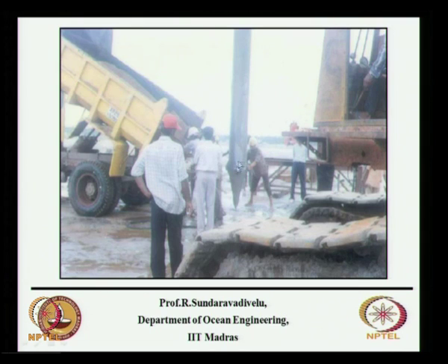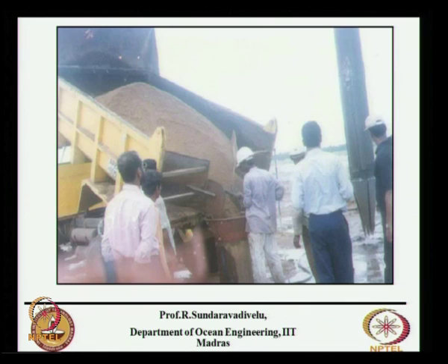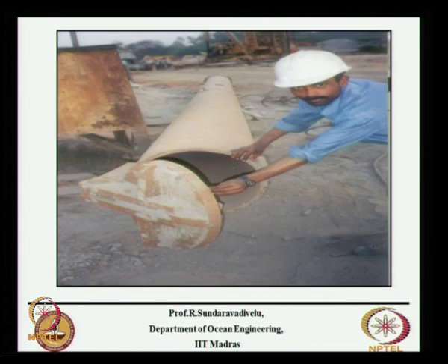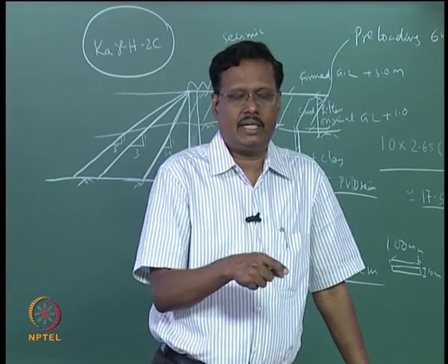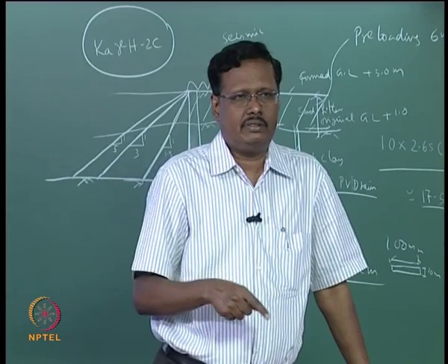So here you are seeing, you have pile driving equipment, what you do is you drive it and there is a bottom opening. You see here this is a steel casing with a bottom opening. There is an attachment to this at the top, once you drive it to a particular level you just release the hook which is attaching the bottom plate.